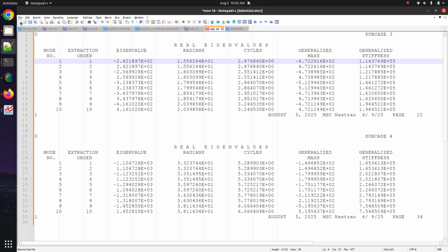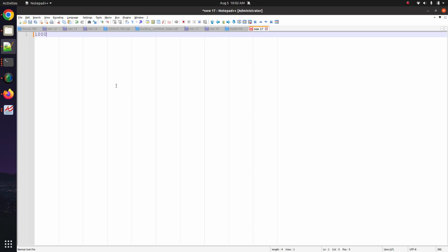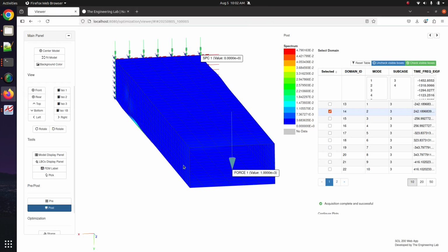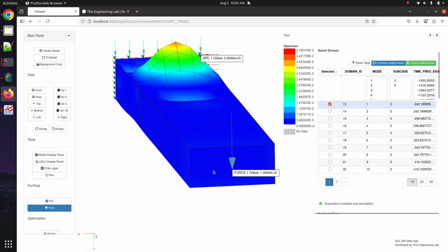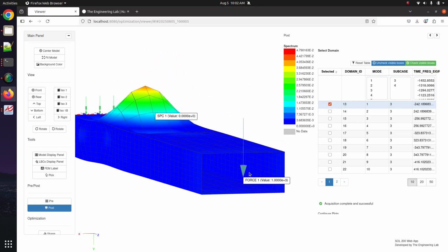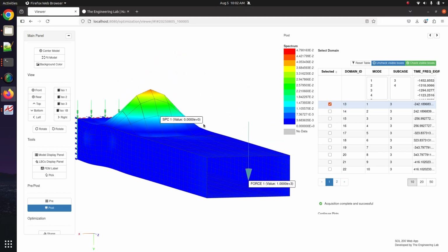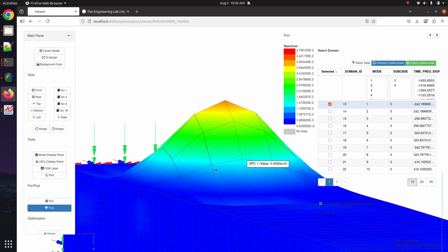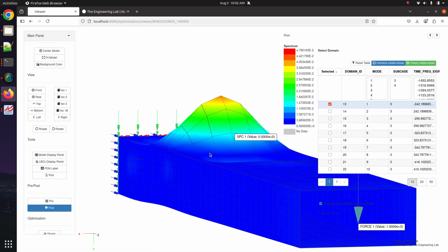Suppose we take that load, so 1,000, and we multiply it by -1. What does that mean? We're effectively reversing the load. So when we reverse the load, when this load goes in the negative y direction, the buckling shape is going to be different. So if this arrow were going in the negative y direction, we get buckling on the top side because now the top wall is experiencing compression.